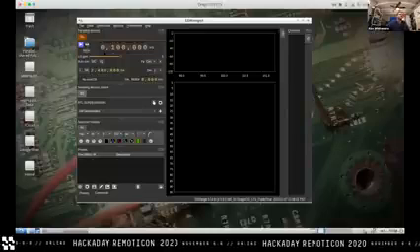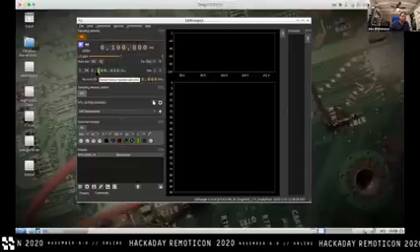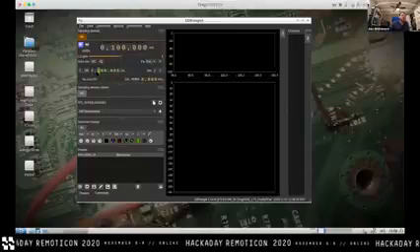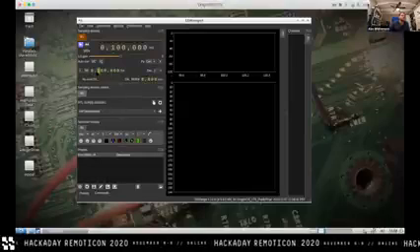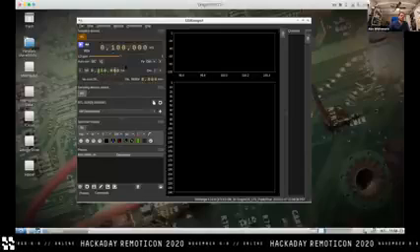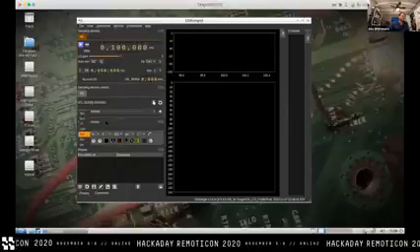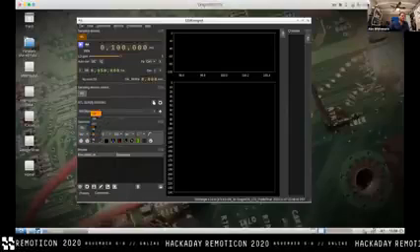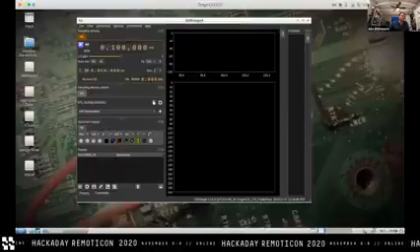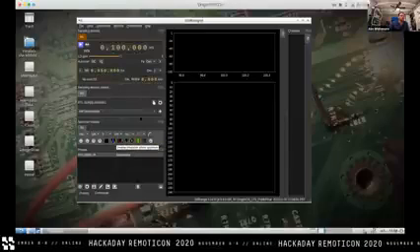But anyway, I am going to throttle that down for now because I fear that this virtual machine isn't going to keep up. I actually don't, but yours might not. So let's go down and knock that sample rate down to 950 kilosamples a second. And let's go down here in the spectrum display. We can leave the window as is. We're going to switch the FFT to 128 points. We'll show what these toggles do later, but leave them as is for now, and we can play with them.